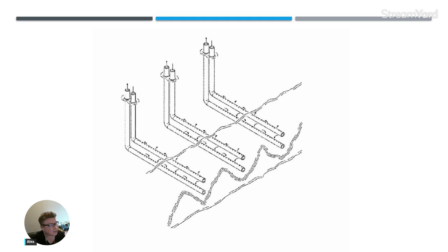So we need the lowest SOR possible. Why? Because if I can reduce that steam requirement, produce the same amount of oil, and reallocate the steam to a new well, not only can I cut emissions, I can reduce energy intensity. I can also accelerate oil production rates because now I reallocated the steam somewhere else that's much more productive. But those reservoirs could be coalescing, they could be merging.